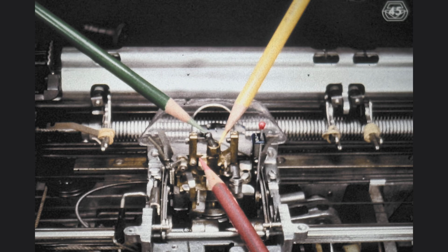As you examine the dog bone, you will find a slot for the pin in the upper ball socket and another slot for the pin in the lower ball socket. The wear in this portion of the rotate mechanism shows first on the dog bone, rather than on the pins in the sockets. It is important to check the wear on the dog bone prior to engaging in tilt and rotate adjustments. We will have difficulty placing the element into its proper position prior to engaging the rotate detent if there is excessive wear on the dog bone. The play which this universal joint allows the type element should never exceed 1/2 of the distance between 2 teeth of the skirt of the type element.